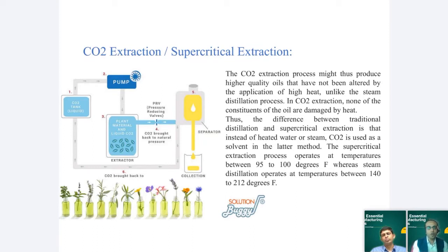Under pressure of carbon dioxide, the product is heated, and with the suction pressure, the CO2 carrying the extract goes to the separator, where it is collected. In this case, the solvents required for each product are different. Steam is also sometimes used. When cold extraction is needed, where the temperature should not exceed 10 degrees Celsius or 5 degrees Celsius, nitrogen can also be used to create pressure, which also controls the temperature. So this is the supercritical CO2 extraction process, which is used for very precise and very pure quality essential oils.